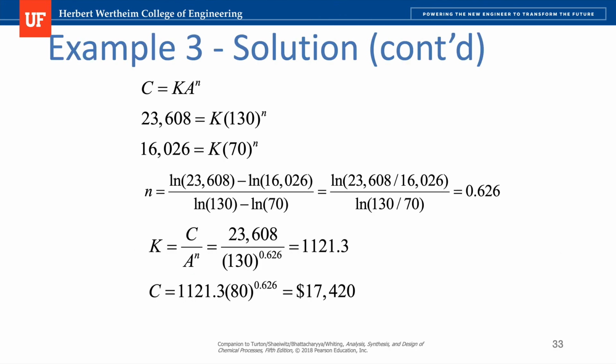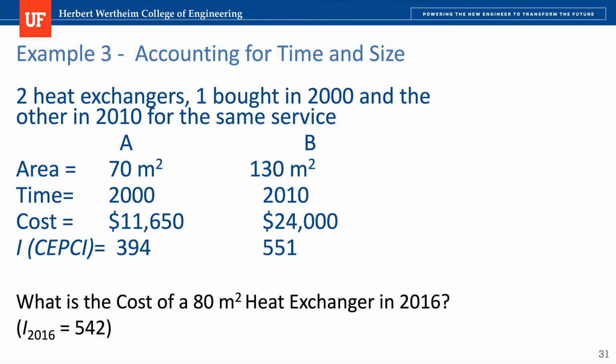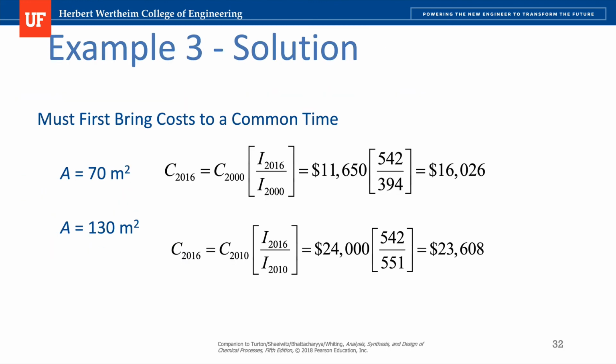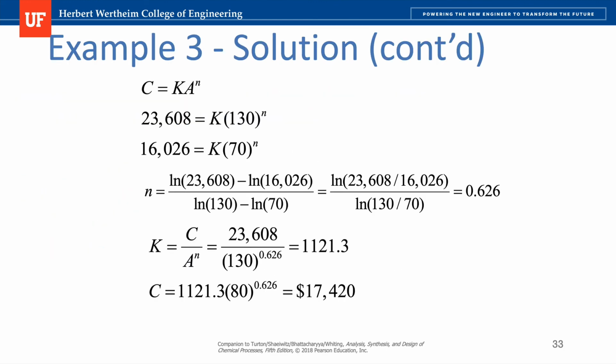Okay. So once again, you go back and forth between these numbers. It's pretty easy going and straightforward. You just have to make sure that what you're doing is the correct thing. I think one of the biggest mistakes is that we compare capacity at different time frames, and they have to be at the same time frame. And then we deal with the capacity, okay? You have two ways. Assume the exponent n of the capacity equation to be equal to 0.6 if you don't have enough information. But if you do have information, make sure to calculate it.